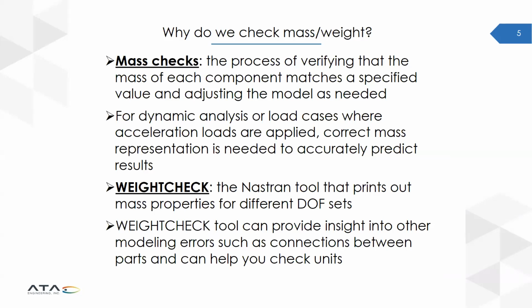Mass checks are the process of making sure that the mass of each component in your model matches some specified value and adjusting your finite element model as needed. And this is important, especially for dynamic analysis.